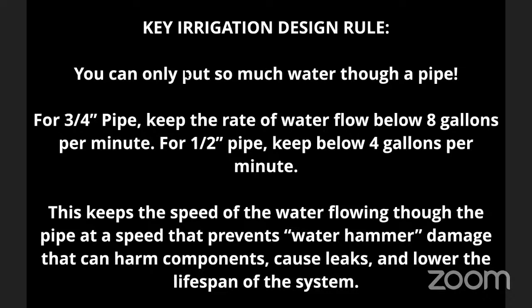Sometimes, like if you have an old rusty galvanized pipe system where there's issues, sometimes that's it, but normally that's not it. Normally the restriction is that the more water you put through the pipe per minute, per hour, however you want to think about it, the more irrigation demand at any given time is needing to go through that pressurized line, the faster that water needs to travel to meet that demand.